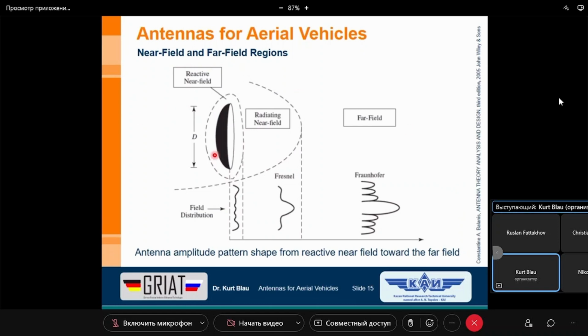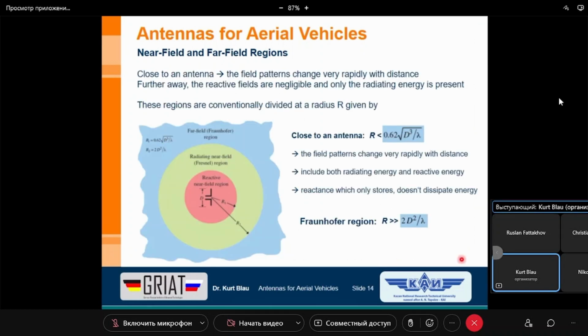And then the wavelength, regarding this D, is very small. In case of satellite reception, we have wavelengths of about 30 millimeters, 3 centimeters. That's 10 gigahertz, and normally it's higher, we have 11 or 12 gigahertz. But for calculation, 30 millimeters is a better value. And if the antenna has a diameter of, let's say, 90 centimeters or 900 millimeters, then you can see that the quotient is 900 divided by 30, which is 30. If we look at the value that is necessary for a suitable measurement distance, it must be much larger than this quotient, 30.